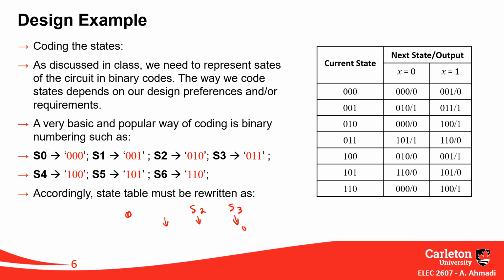I can also look into a state diagram. If there is a transition between two states, I make their codes similar and different only in one bit. Well, this is a more advanced discussion. This is something that you might want to consider in future in your real design.